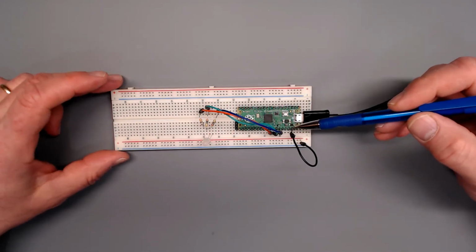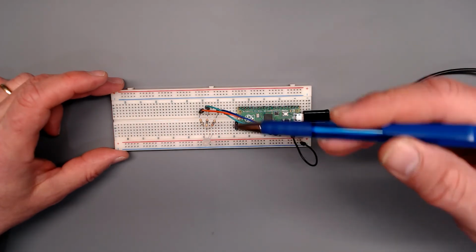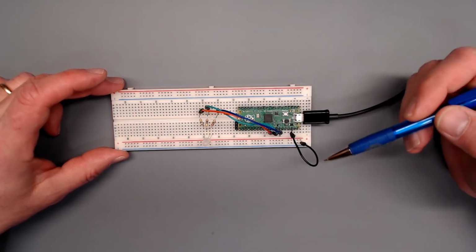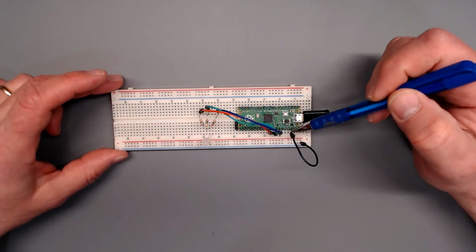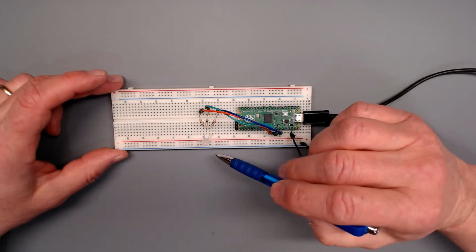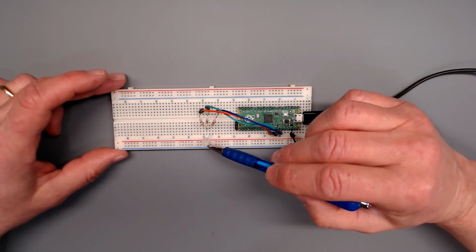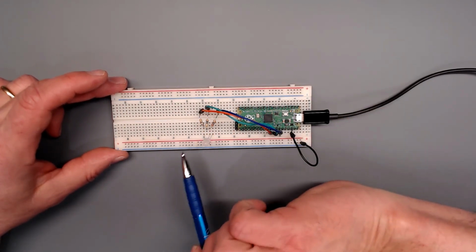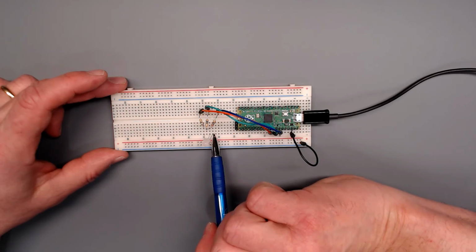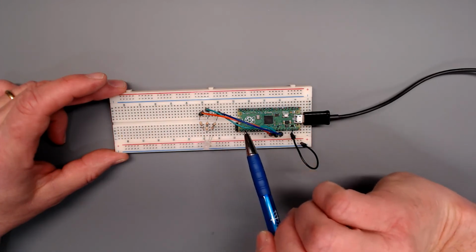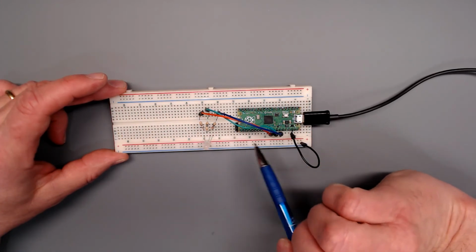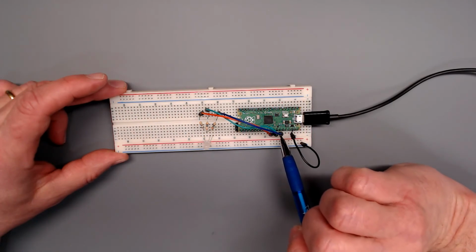Coming over to the actual breadboard, you can see the connections are identical. It's just inverted on this axis, the y-axis, and I don't know why I did that, to be honest with you, but we've got our ground wire coming over to the ground rail, pin 1, plugs directly into the ground rail, and then we've got from left to right red, green, blue legs going through 68 ohm, 10 ohm, and 10 ohm resistors into the red wire, going back to 26, green wire 27, blue wire, GP number 28. Now let's take a look at our first program example, and it's going to be very, very simple.